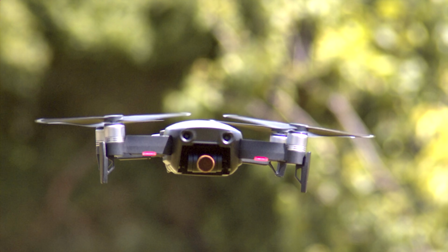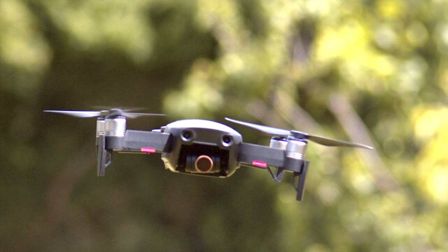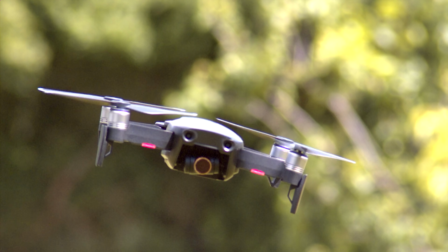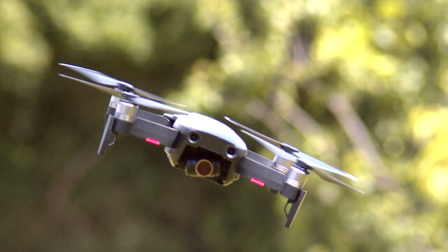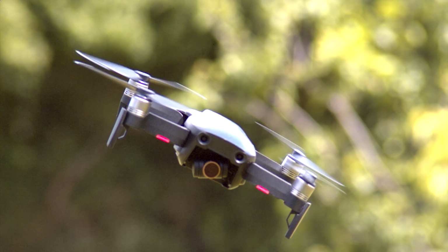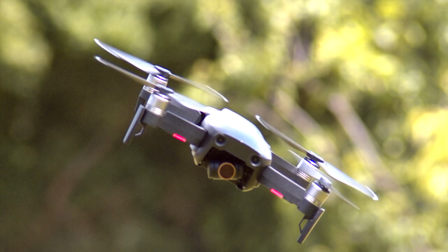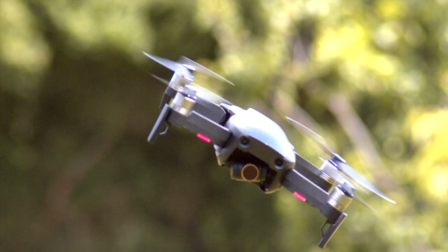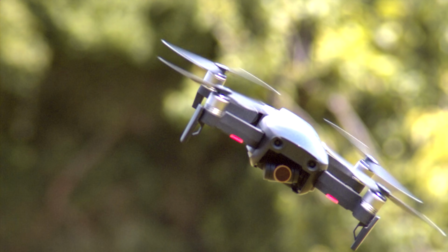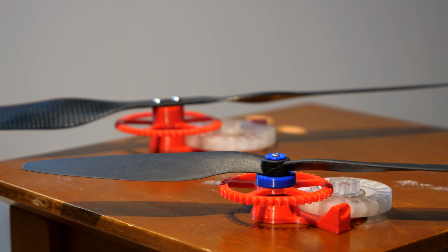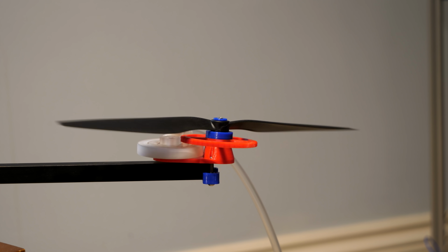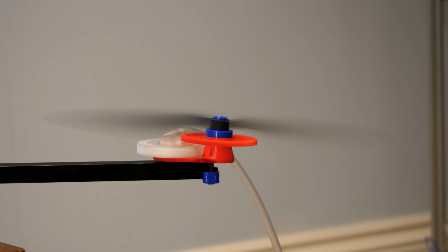But aside from the thrust produced, a quadcopter is controlled by varying the speed of its propellers. And generally smaller propellers have less rotational inertia, which means they require less torque to change speed. And since the turbine I've designed doesn't have much torque, I'll need some smaller propellers. This means adjusting the turbine gear ratio to match the optimum RPM of the smaller propeller. The only problem is I can't get it to produce anywhere near the amount of thrust of the larger propeller, which I can only narrow down to the smaller propeller being less efficient.